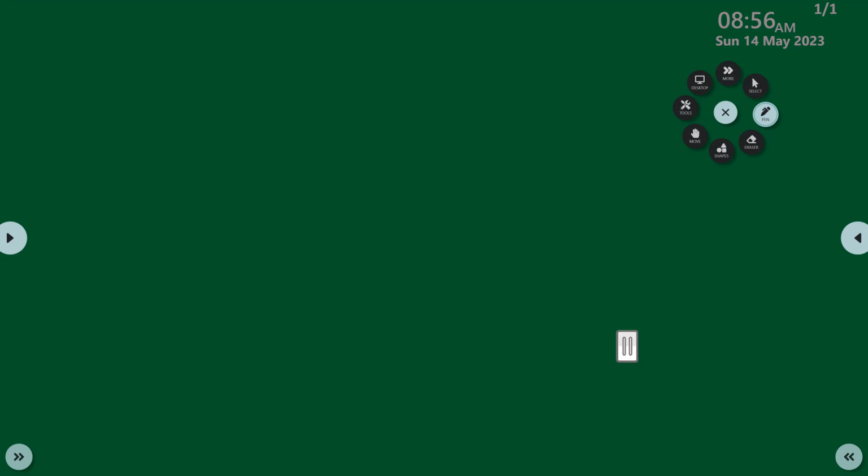Let's say you write A and B. Then the tool understands this to mean an AND gate. How the AND gate performs, how it is designed with CMOS, how it produces output, all this mapping will be taken care of by the tool. You only need to write A and B in the language, and AND means it will consider it as an AND gate.